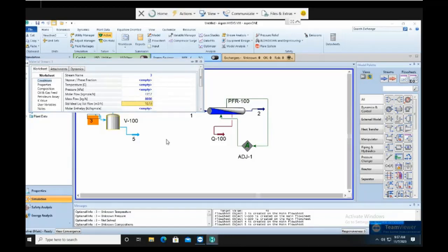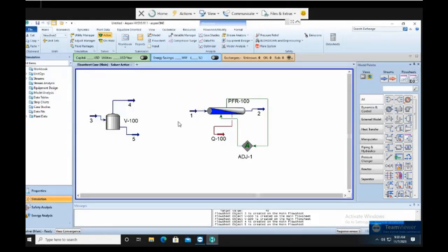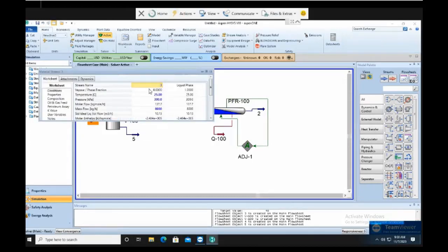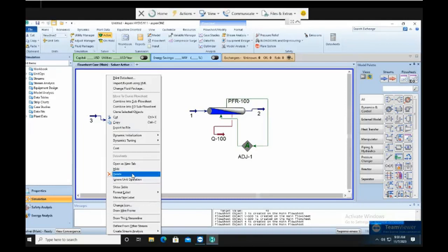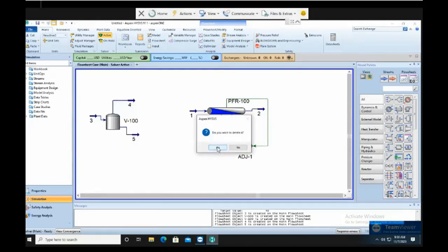Okay. So in this case the pressure, I don't know, 3 bar. The pressure is 3 bar, the temperature 25. So that is what we have, the feed going into this. At temperature 25, acetone is in liquid form. So why buy something at a high pressure with a vapor phase when it's much better to store everything in liquid phase. So in here is 0, so you can always hide this or you can delete that. Not an issue. Yes, we can delete that.